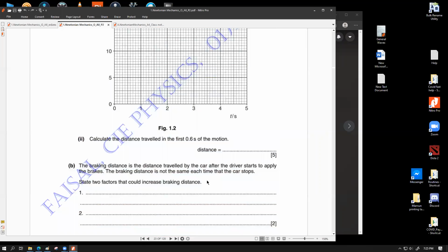It is also possible that the braking mechanism had some air in the system, so it was not applying full brakes. Or the brakes were not pushed all the way down. The brake lever was not floored, so it was halfway pushed, so there was less braking force available.